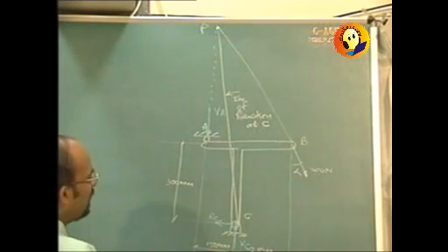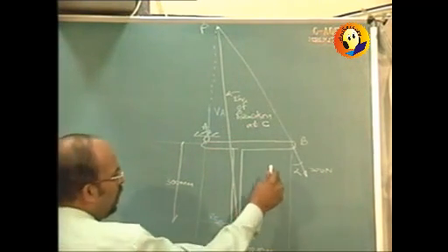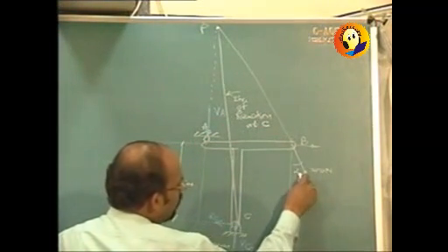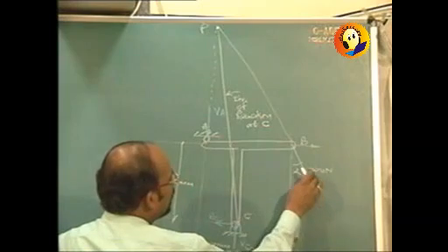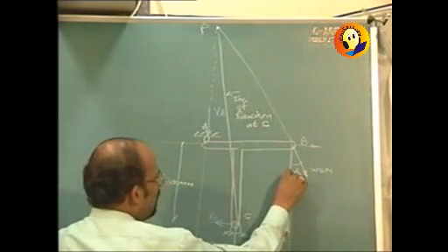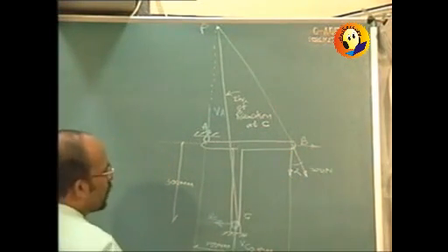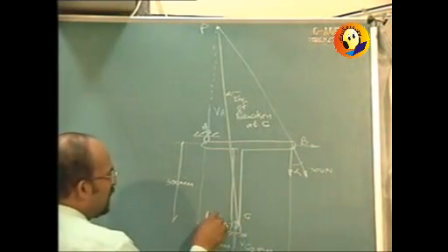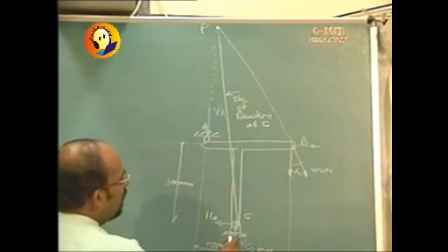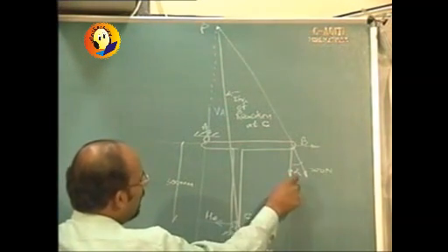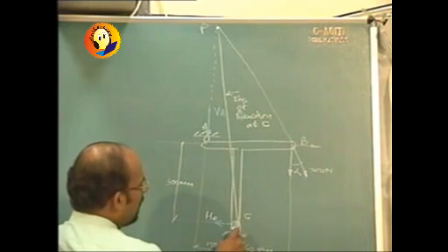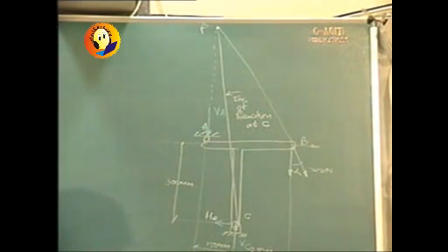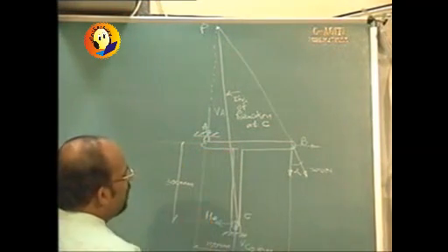You will also find that over here you have a horizontal force at B acting towards the right. If I take the components of 300, it is going to be 300 sin alpha towards the right, and 300 cos alpha downward. The force towards the right will be balanced by the horizontal reaction at C, HC, and the downward component will be balanced by the vertical reaction at point C as well as the vertical reaction at point A. And this is trying to rotate, and A will prevent it.